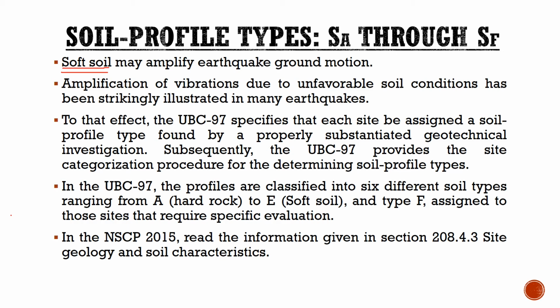So amplification of vibrations due to unfavorable soil conditions has been strikingly illustrated in many earthquakes. So amplification of vibration guys, due to poor soil conditions. To that effect, the UBC 97 specifies that each site be assigned a soil profile type found by a properly substantiated geotechnical investigation.